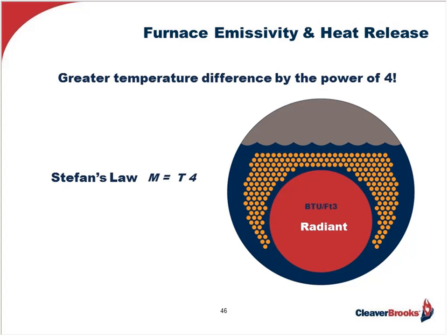So combining this significant difference with the mass flow and the turbulent velocity caused by the burner's combustion air fan, and if designed right, the furnace takes on a much larger role in converting heat energy to steam or hot water. And the reason for that is found in a principle of physics developed by Stefan Boltzmann and involving furnace emissivity, which is the ability of a black body, such as the furnace, to absorb heat energy with perfect efficiency at all electromagnetic wavelengths.